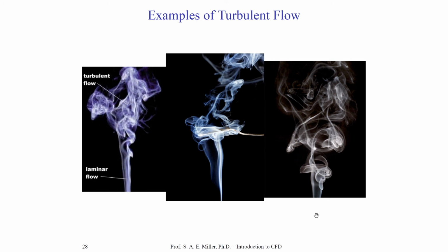the energy. So you can see as it comes up, the scales of turbulence are transitioning from laminar to transitional and become larger and larger to integral scales, which then become fully three-dimensional turbulence and break down to a full turbulent cascade, and the energy travels down the cascade and dissipates to heat and acoustics. It's a beautiful process.